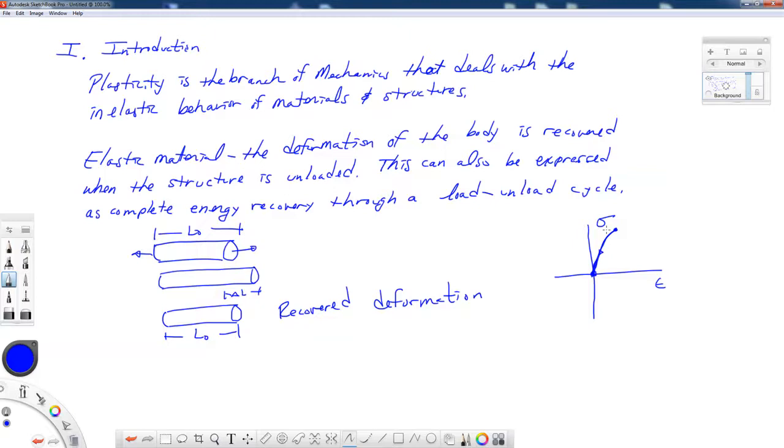So there may be some development of slip systems and so forth. In fact, that's the basis for metal fatigue when we're below the yield stress of the metal. There are permanent changes that occur in the material. So elasticity, in a lot of instances, is an assumption that we're going to make to make our math and our analysis a little bit easier, but it is just that, an assumption. And just like any assumption in engineering, we have to be cognizant of when those assumptions break down.